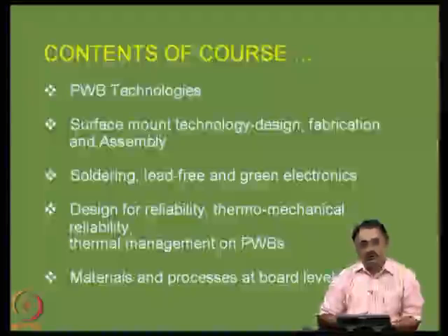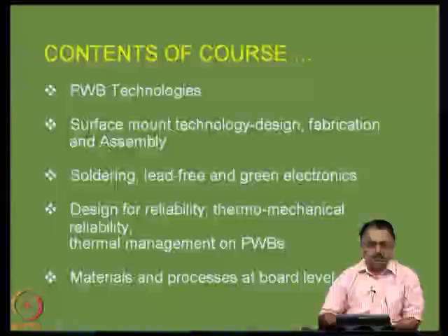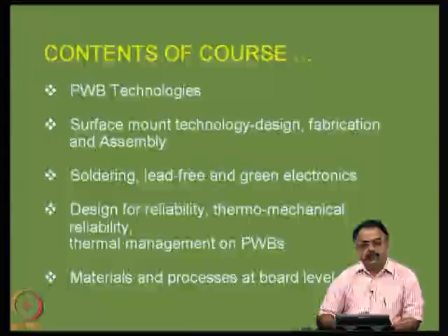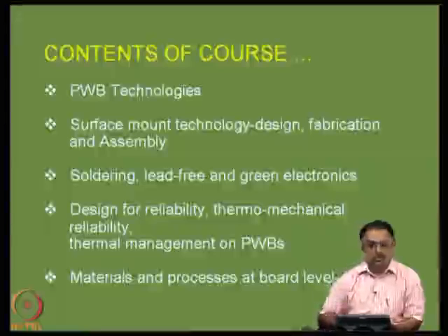So I am going to devote a very substantial part of the time on evolving a green product. When I say green, it is environmental friendly. And lead free, why should it be lead free? Lead is a metal, and till now it was used as one of the elements for attaching a component onto a substrate. Because of the health hazard posed by lead, lead has come into a legislation, lead has to be removed, and we are now trying to see how to use lead free materials for attaching components onto substrates.